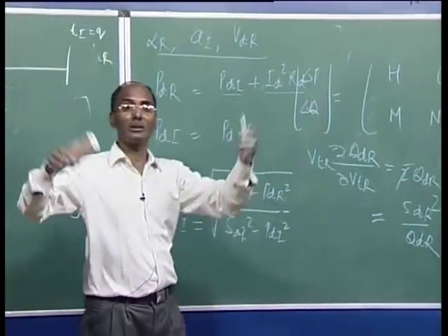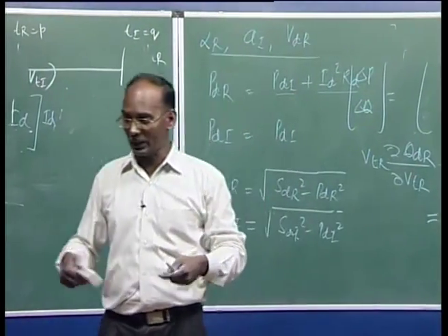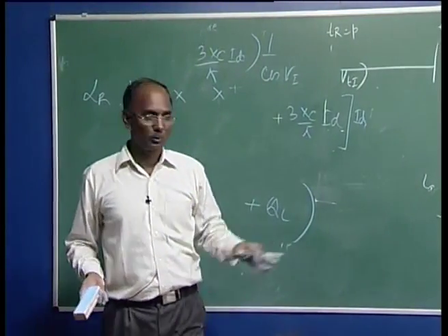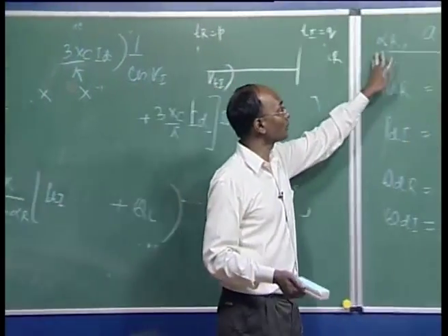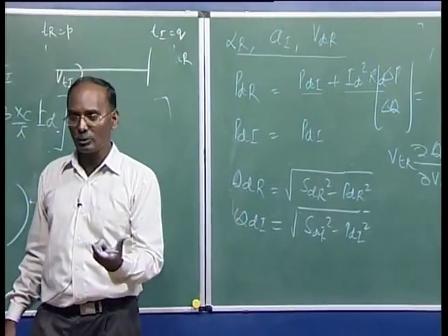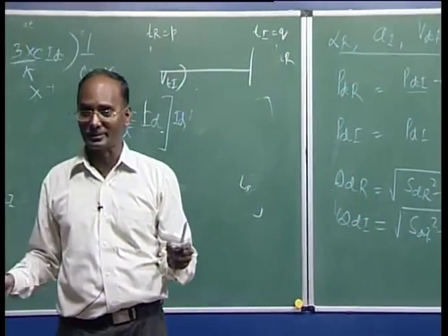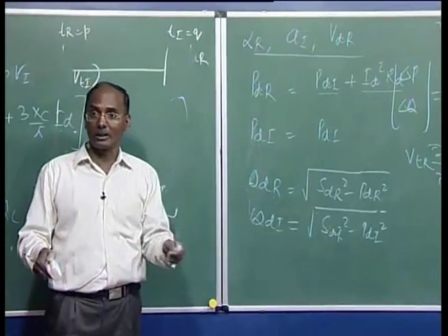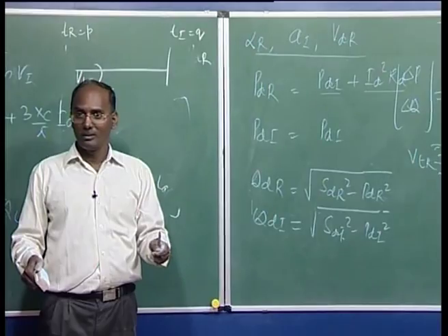Suppose alpha comes to something like 180 degrees, or A comes to 200 in that calculation, that means there is no solution. So once you converge, you have to check whether these variables are within the specific limits or not, just as you check the Q limits of the generators. Similarly, you have to check the limits of the HVDC variables. Then your control mode will keep on changing.